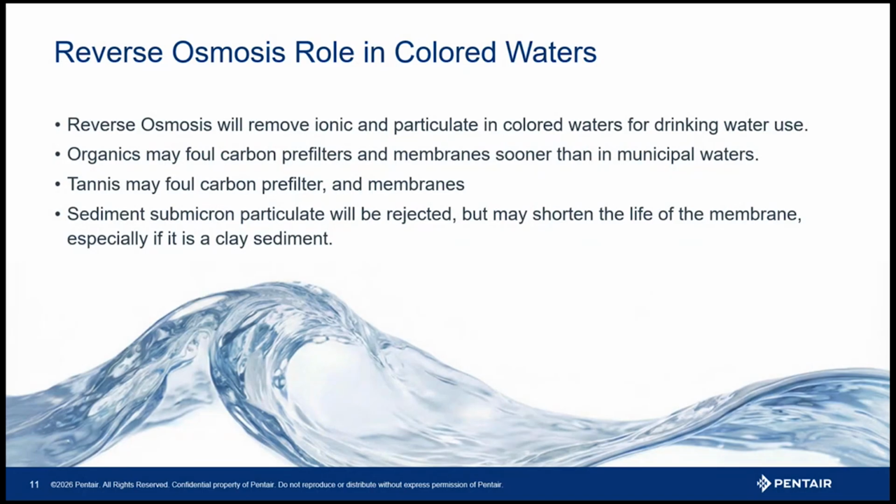So if you're aware that you're selling a drinking water RO into an untreated well water situation, it's just a good conversation to have with your customer that these things will shorten the life of these membranes compared to other places because of the water quality. And you may want to install a pre-filter in front of it to deal with some of this stuff before it hits the RO, and have a staged filtration before your RO to preserve those valuable RO cartridges.